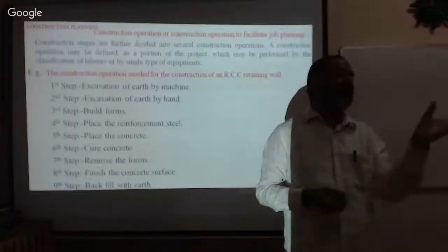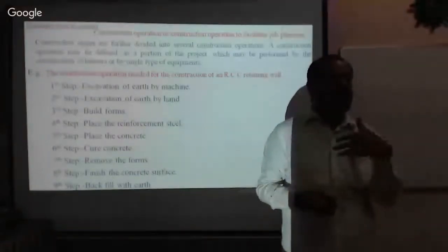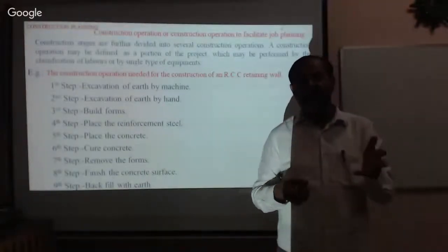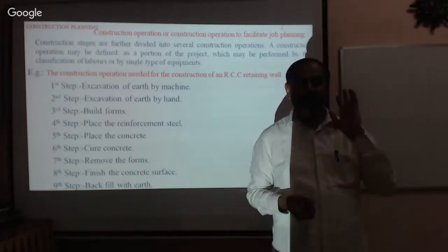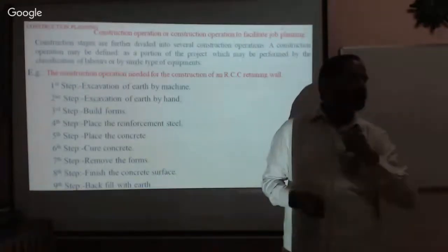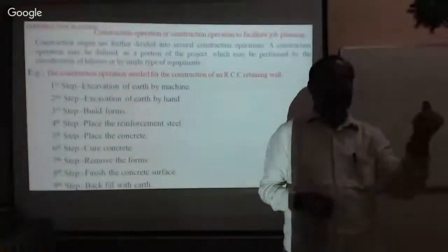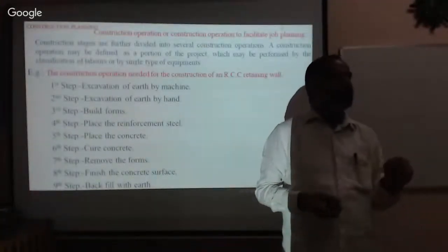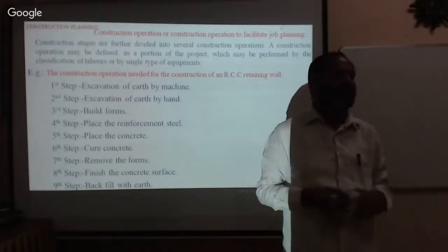For various authorities, I told you already. I will come back to this again now and then. I will keep telling this because we need to approach the various authorities. Therefore, the first job: go and collect the data from the ground, then collect the foundation soil details, because the soil detail decides your foundation, isn't it?